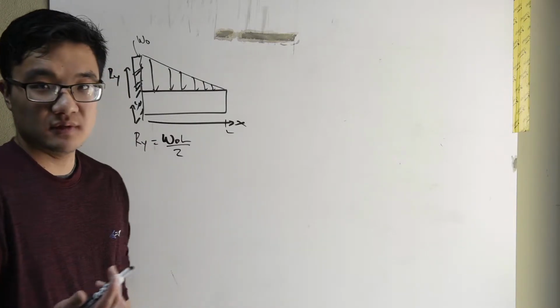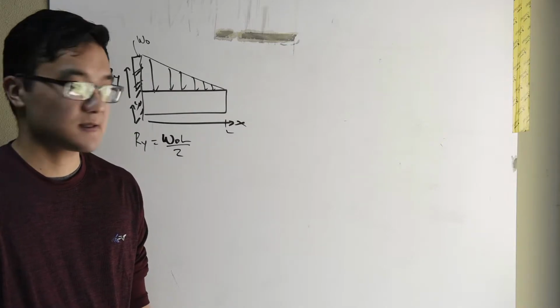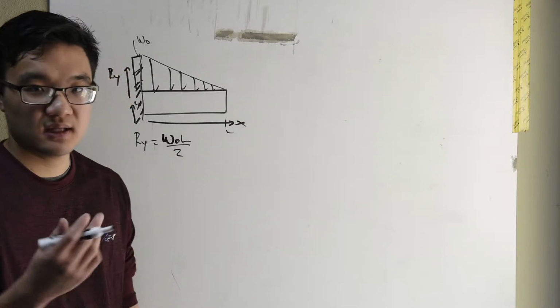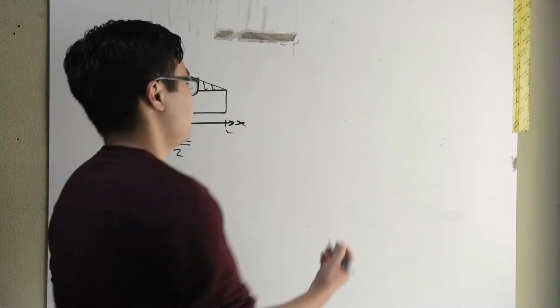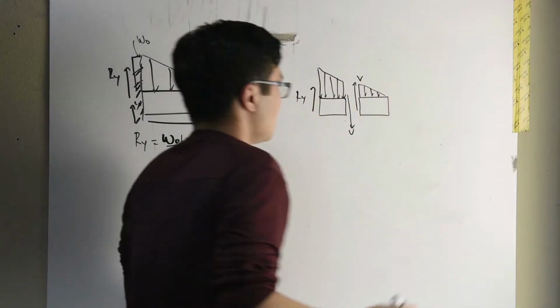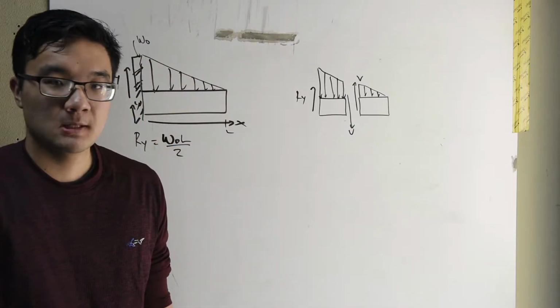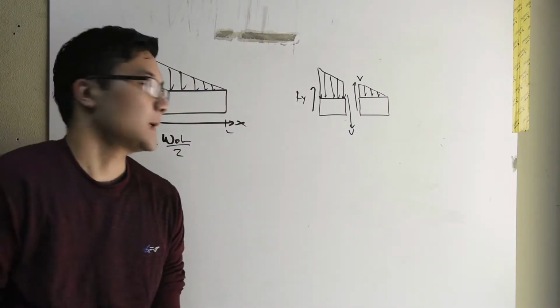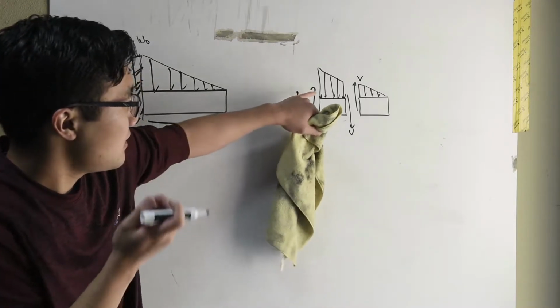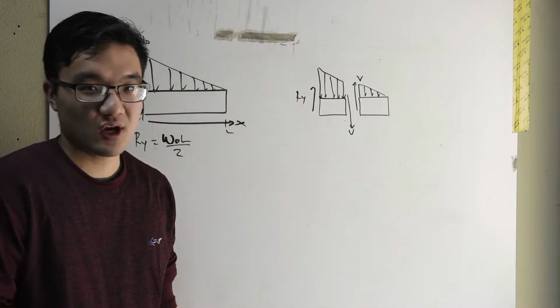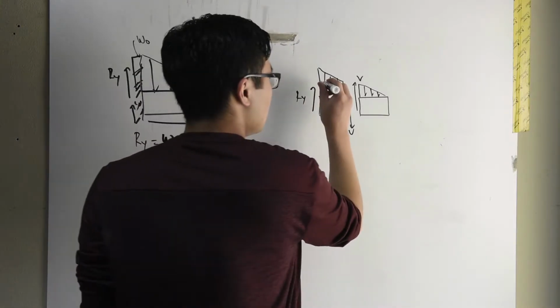So now what we'll do is we'll draw the same diagram we drew last time. We'll draw that beam cut in half at any point and show what the loading criteria looks like. Should look something like that. But now there's a little trick here, because if I want to move left to right, that's not a triangle anymore. That's a triangle on top of a rectangle.